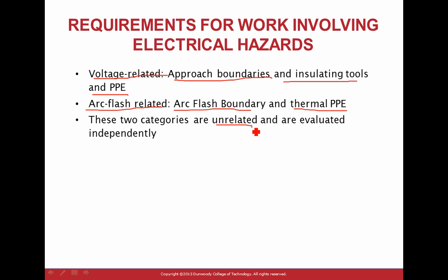So when you work energized, like I said, there are two different things. One is the shock hazard. One is the arc flash hazard and the blast. They're two completely different things, and you are to pick the equipment and the tools that protect you from both. Cool? All right, so let's go into that one.